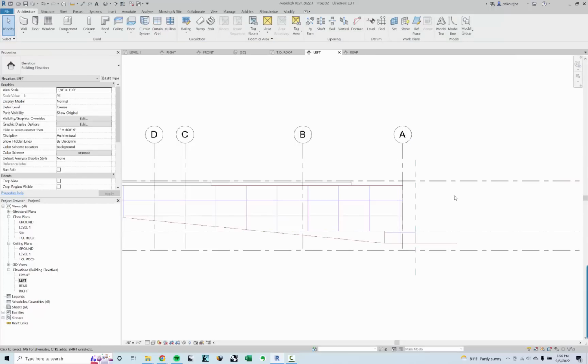So that's very helpful in being able to determine the location of different things that, again, you may not want to print. You don't want too many grid lines. You don't want too many levels. It's going to become really difficult to manage later. I cannot emphasize how important it is to minimize the amount of levels you need, because once you start drawing things in plan and section, it'll start constraining to different levels.